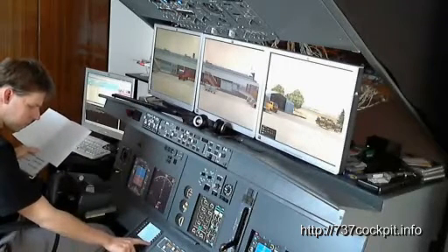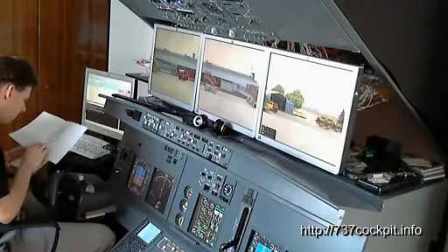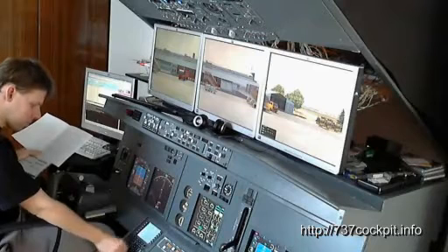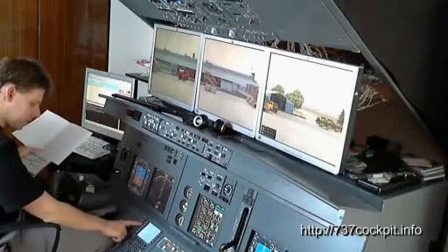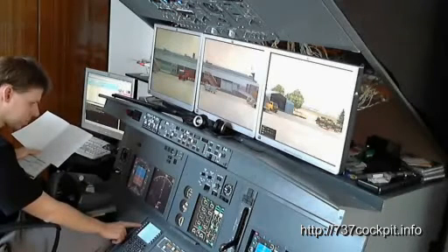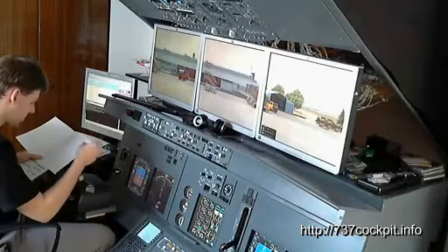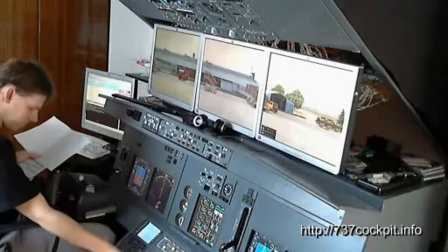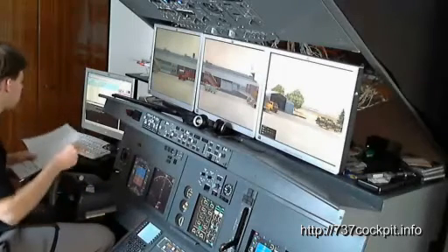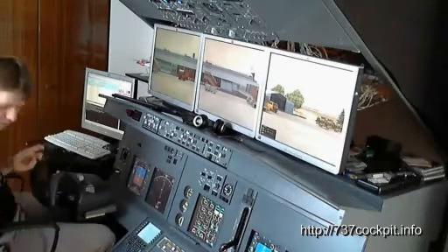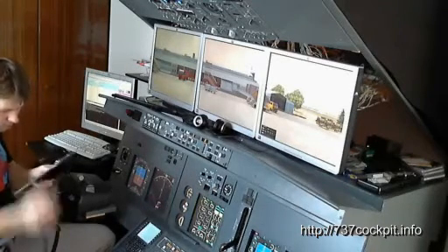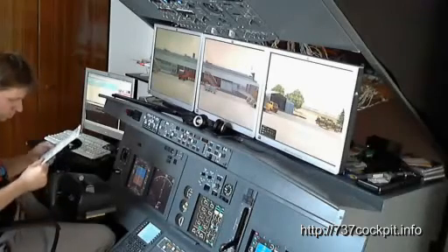On the next page we enter our outside air temperature that we have calculated before with 61 degrees, and with a T-rated takeoff that gives us 88.5% of N1. So we cannot enter the departure height now as we don't have the clearance from the ATC. So we will call ATC. Before we call ATC, we've missed one thing.